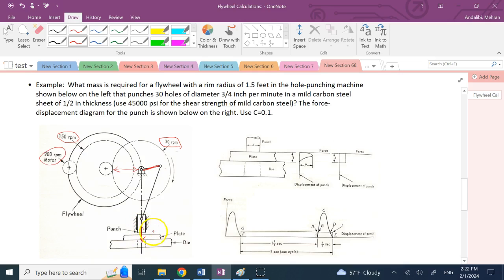And when this piston goes up and down, you have a metal sheet plate that you want to punch a hole into. You put that plate on this die, which has a hole already. And when this punch drives through the plate using a lot of force that is in this member, the vertical component of that will force that punch through the plate, makes the hole in the plate, and it punches the plate basically. Okay, so that is your punching mechanism here.